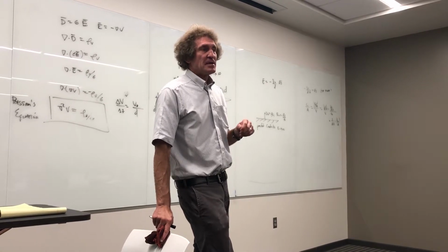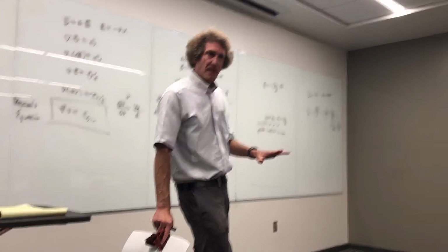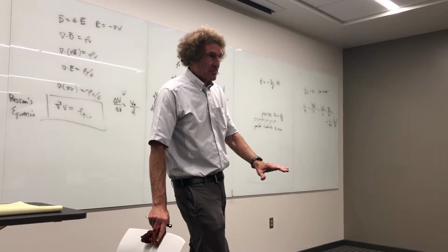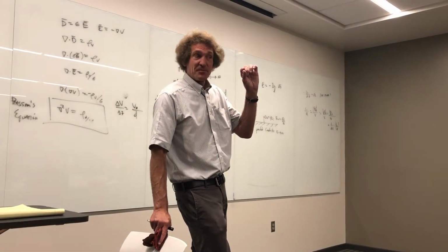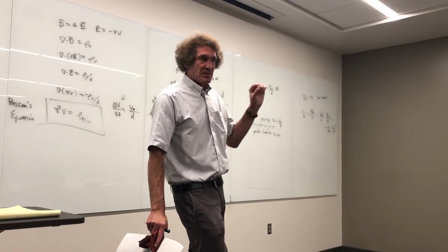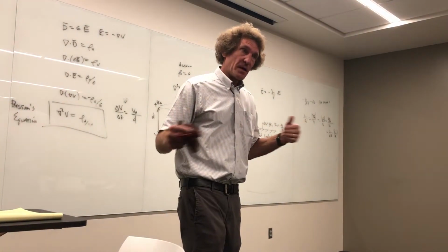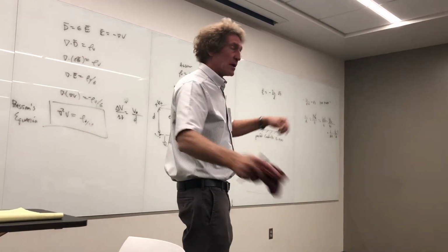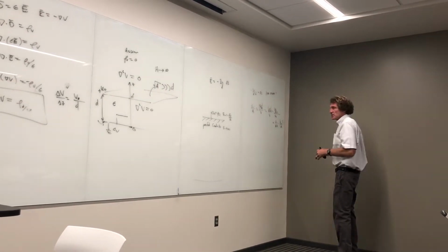You can make a fairly decent, interesting capacitor. Did I tell you about the aluminum foil in here again? Yeah, I did. Well, if you just take sheets of aluminum foil, put wax paper and then aluminum foil on top of it, you've got a capacitor. Now, if you think about the separation distance, that wax paper is very small. I don't know, maybe 30 microns or so, 40, 50 microns, something like that. But the aluminum foil can be a foot or 1 or 2 feet in width, right? And it's as long as you want. That's sort of like the relative dimensions of capacitors in general.